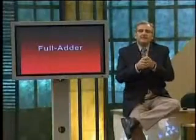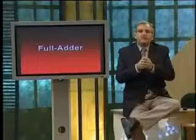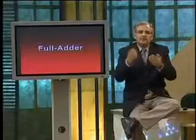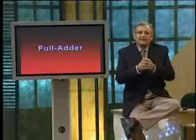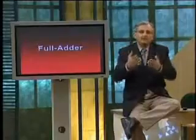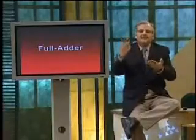And lastly, the input combination 1, 1, 1. What is the sum output? It has to be a 1. And what is the carry output? It is again a 1. So now we have two outputs for the sum output and the carry out output.